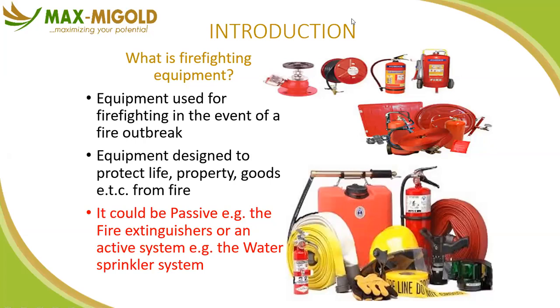What we're saying is that the material used to construct the building, the selected materials, should be fire resistant, from the door to the ceiling to the paint to the decorative material and what have you. And in some cases, when you don't have that luxury, because maybe the building is leased or even rented, so you can't actually change a lot of things, we're also saying don't come and attach additional flammable materials.